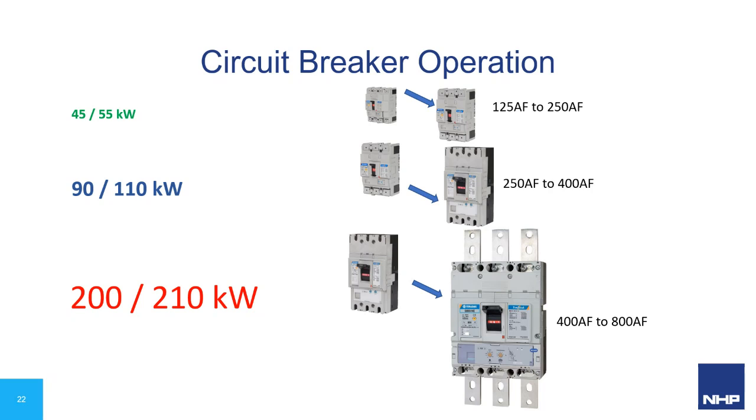The discovery that the electronic overcurrent relay was not detecting enough energy let through in the time it took to calculate and fire the magnetic hold trigger was a bit of a light bulb moment. Our conclusions were then proven correct, and the breakers were experiencing contact repulsion with each start. However, the electronic OCR was not forcing a trip.